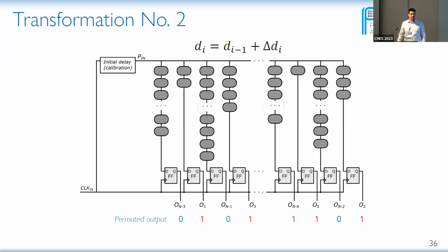Thank you for the great talk. For the TDC, we know that there is a non-linearity and some bubbles in the chain. So for the routing, do you face the same problem? Does it affect the result? Thank you. Yes, TDC has non-linearity, especially since carry chains are trying to implement the propagation as fast as possible. And the same goes with RDS. We have not evaluated the linearity of our sensor, but because we let the tool decide which routes it's going to use, it is completely feasible that in this figure there are some differences that are non-linear.